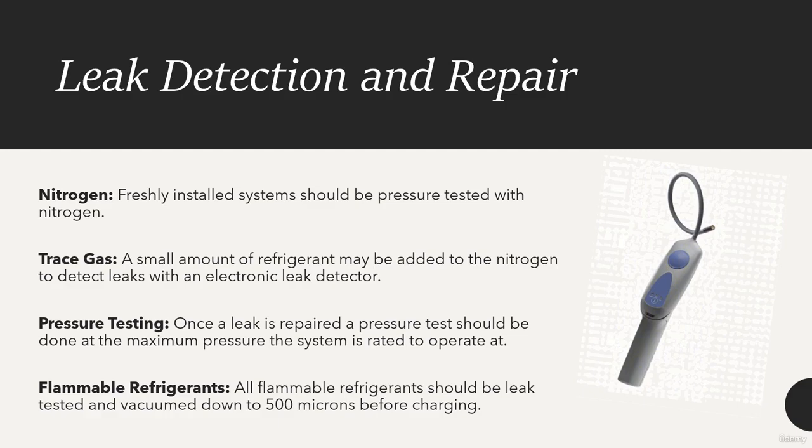Pressure testing is, once a leak is repaired, a pressure test should be done at the maximum pressure the system is rated to operate at, which would typically be done with nitrogen. All flammable refrigerant should be leak tested and vacuumed down to 500 microns before charging.